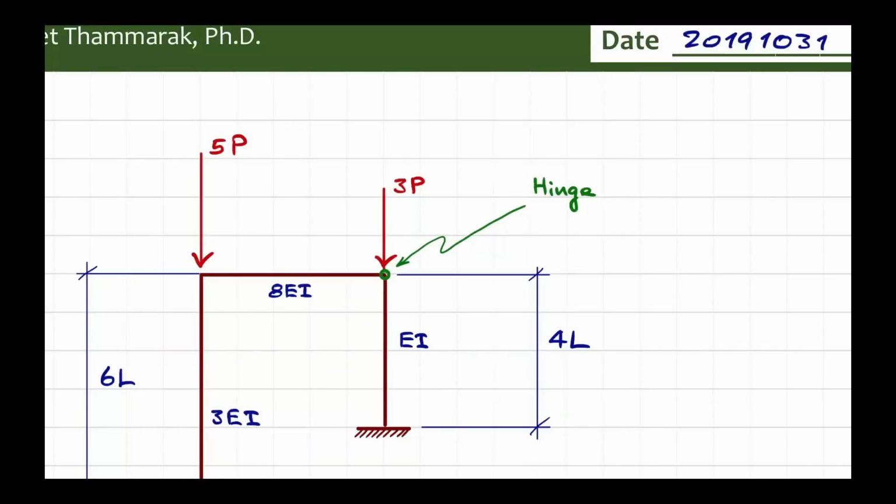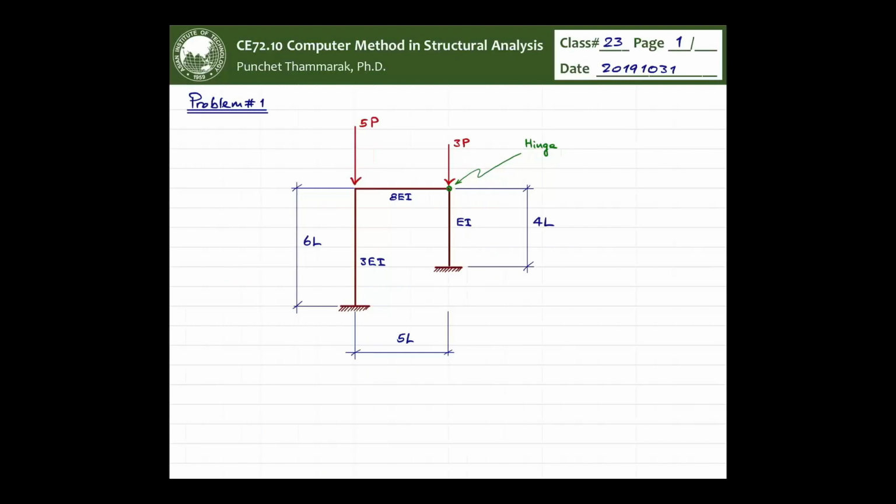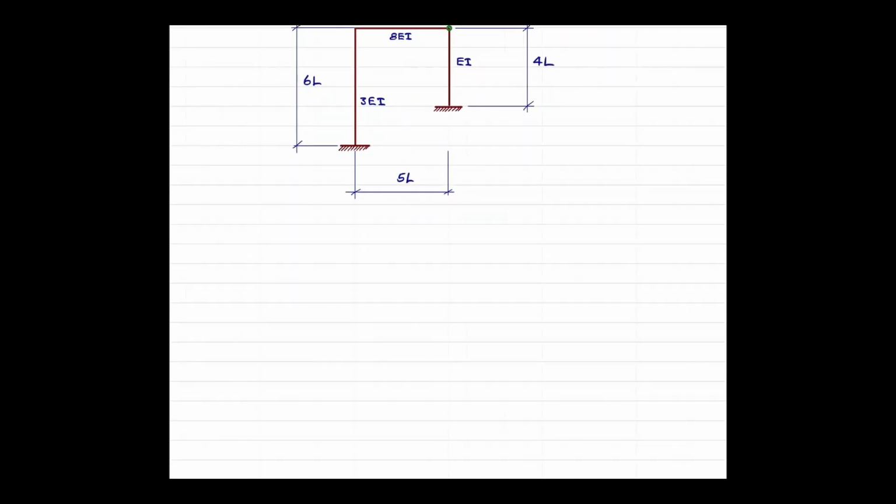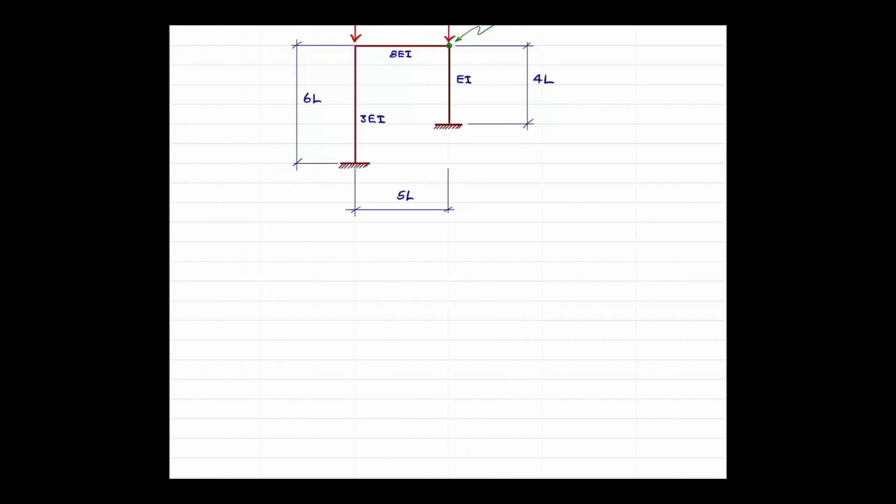You know that it is a hinge. But the second problem will be totally different. The case like this, where you only have the load concentric through the column, is quite rare. In reality, you apply the load on the beam, on the slab, which transfers the load to the column, and basically at the first round of the analysis, you do not have the predetermined internal axial force in each individual column. So let's take a look at the second case.